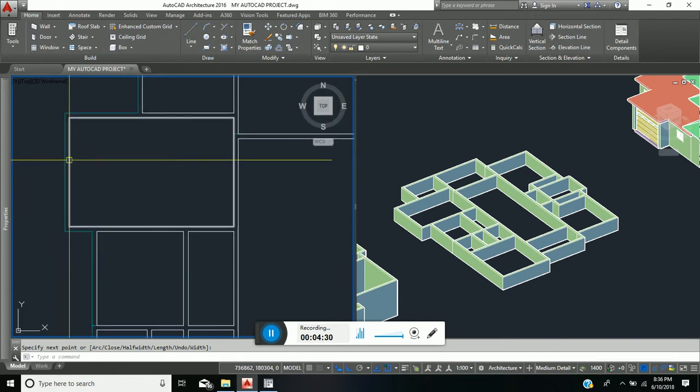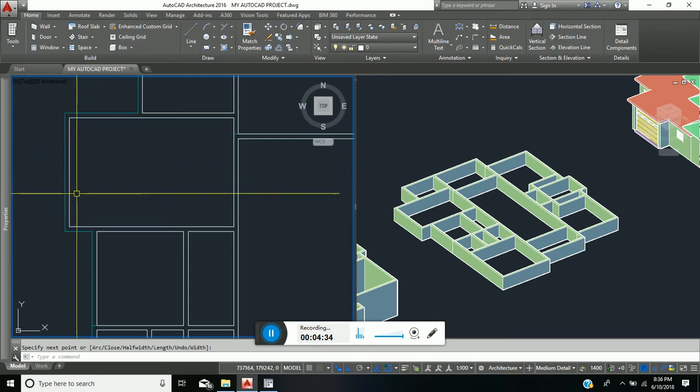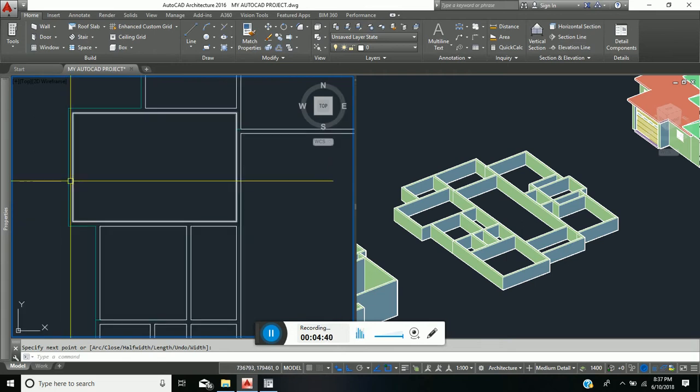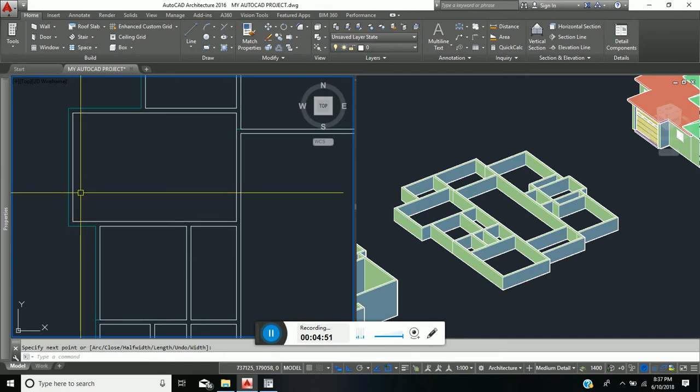We do that because we would want to now offset the foundation dimensions on the inside. Usually a foundation width is expected to be minimum 3 times the wall thickness, and so what we would want to achieve are lines the same. Since these are 150 millimeters, we would want at least 150 millimeters on the inside as well as on the outside.